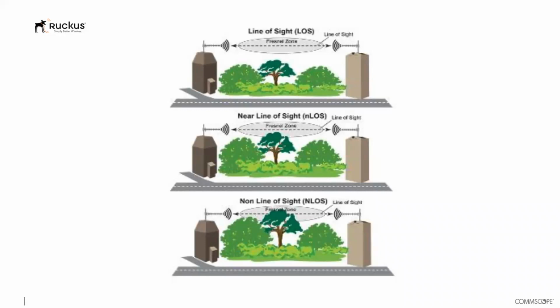So this is where you can use, like I showed earlier, Google Earth Pro or some kind of elevation profiling tool that you can put 2 points in and see what the terrain is in between. What you're looking for is to make sure that the Fresnel zone is not obstructed. If it is obstructed, like you see in the bottom picture there, the way you get around that is to raise the antennas up. You can put the antennas a little bit higher on masts and get free of that.